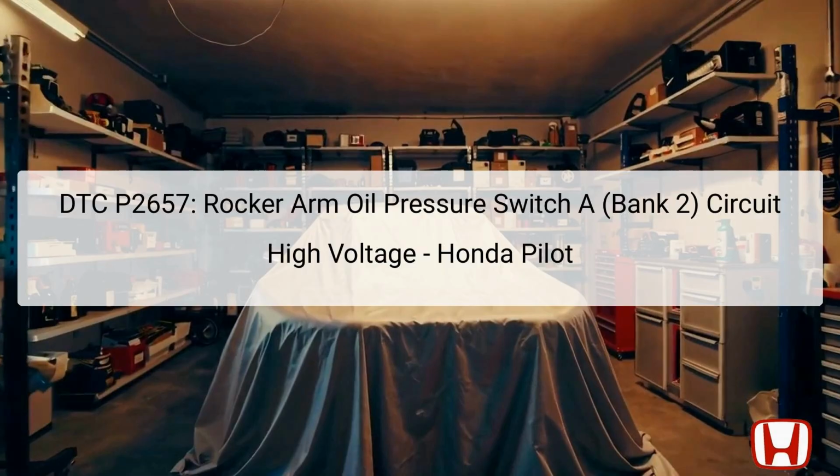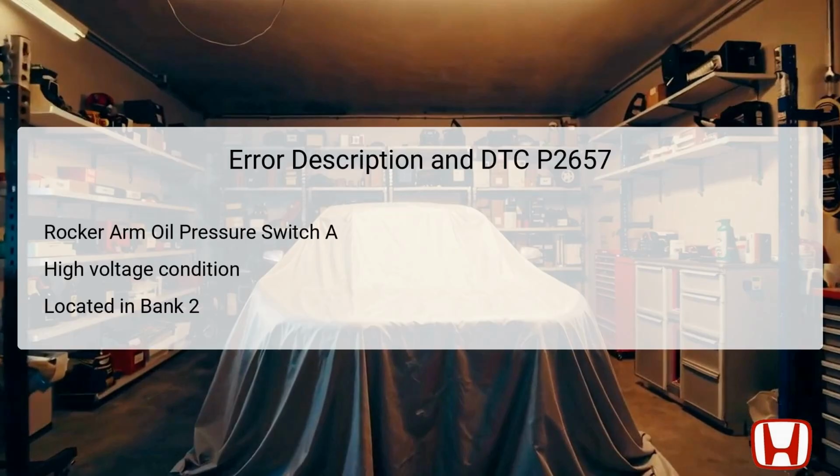The switch is usually located on the cylinder head, close to the variable valve timing actuator for easy access. If this switch fails or reports incorrect readings, it can affect the engine's timing and overall operation, triggering the P2657 code. To address this issue, it's essential to follow the detailed troubleshooting process to identify and rectify the root cause of the problem. The rocker arm oil pressure switch A is a component responsible for monitoring the oil pressure within the engine, particularly for Bank 2.